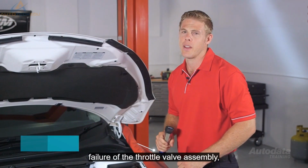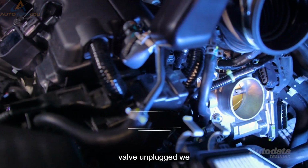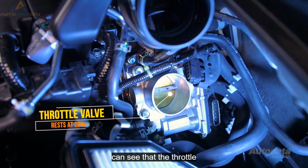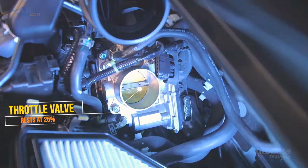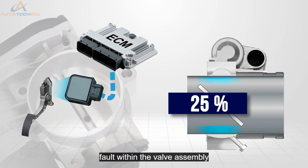If there is a complete failure of the throttle valve assembly, the vehicle may still be driven. With the throttle valve unplugged, we can see that the throttle blade rests at around 25%. This is a design feature in case there is a fault within the valve assembly. Engine torque is regulated using controlled misfire events.